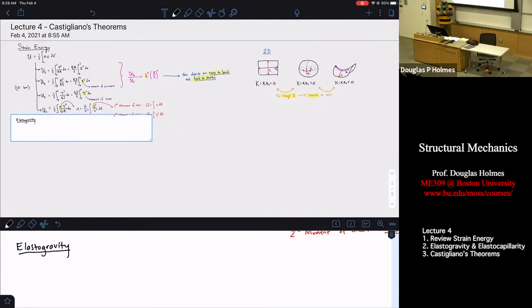And we could say, well, let's just find out what length scale gravity and bending balance each other. We know the length scale for bending. Okay, so let's do this really quickly. We know that our bending energy is equal to EI over 2 times kappa squared dx. We can approximate and say, well, let's not worry. We only want to know when gravity is going to just start to bend our object to a small amount.